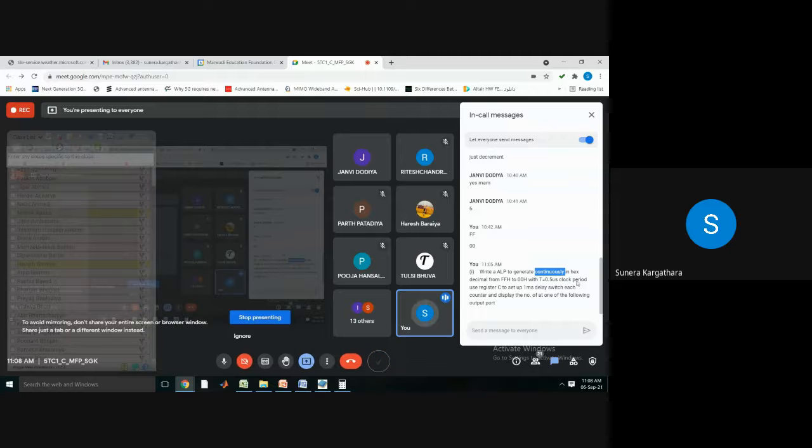So you need to design a hexadecimal counter, क्यों बोला है? Because we are counting from FF to 00. We don't want to design a counter which will only count once, but it should count continuously, right? So that's why you need to take a value FF into your counter. You will decrement it. You will check whether it has become 00 or not. If it is not, again it will go and decrement. But if it is 00, then again it will go and load your maximum value. Ritesh, are you getting me? Yes, ma'am. Correct. So how to design that counter, I think everyone can do.